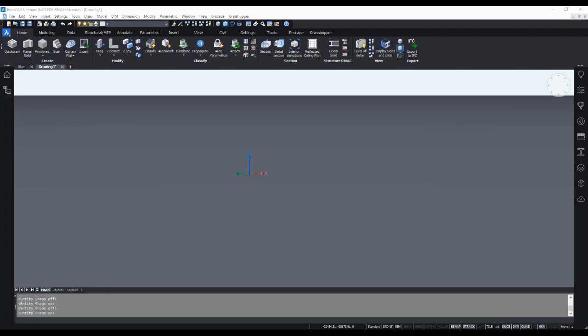Now there are a couple of other configurations that we're just going to type at the command line. The first one is DMEXTRUDEMODE. And notice as I start to type that I'm presented with some options that might match what I'm typing. Once I've got those options, I can use my arrow keys on my keyboard and go ahead and select the item and just hit enter.